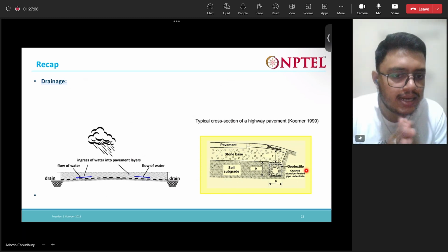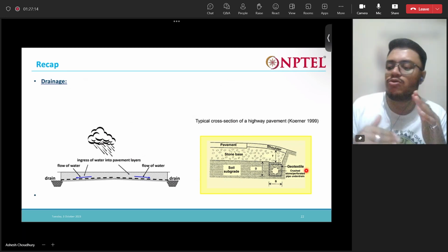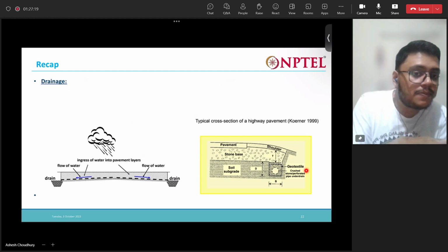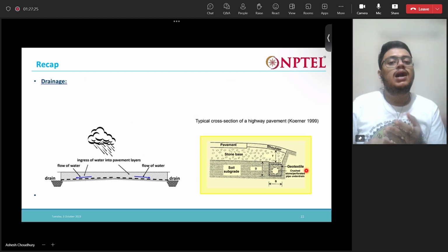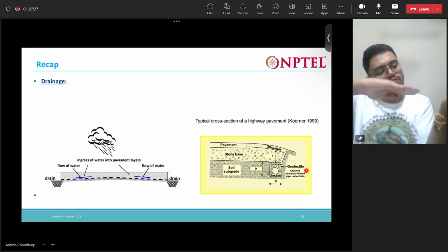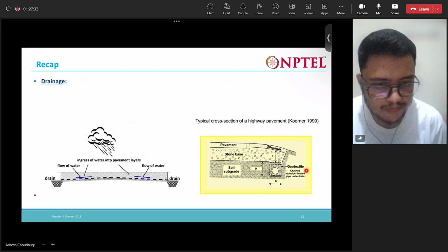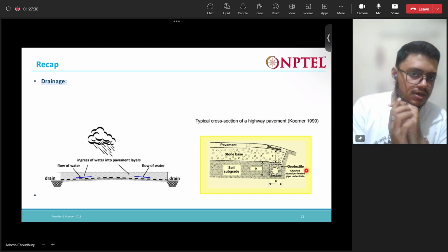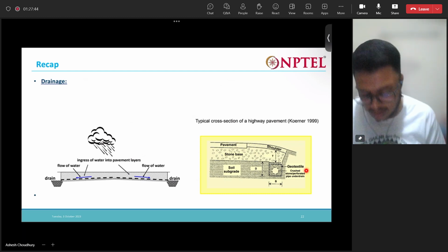Now whatever we will be studying is related to the in plane flow, that is the drainage in plane flow. For the filtration, this cross plane flow or the permittivity is important, right? But for drainage purposes, it is the in plane flow, that is the transmissivity. The flow along the plane of the geotextile is important, not the cross plane flow. The cross plane flow is important in filter section, but for drainage the in plane flow is important.